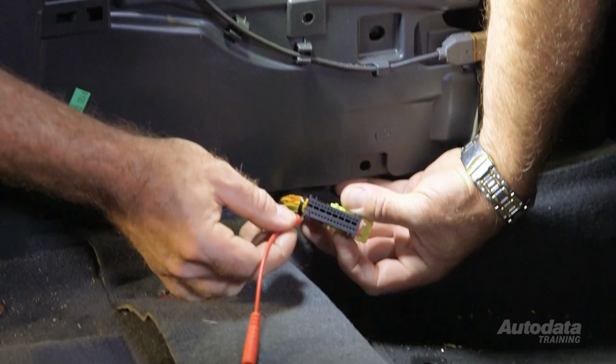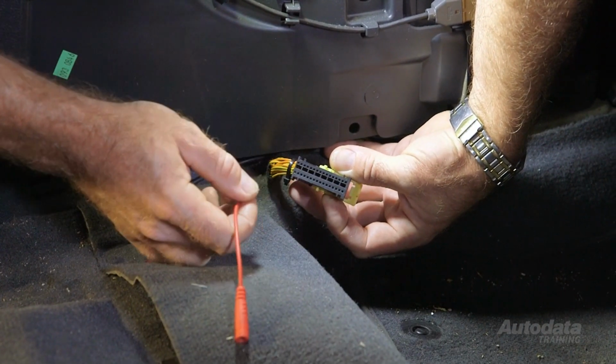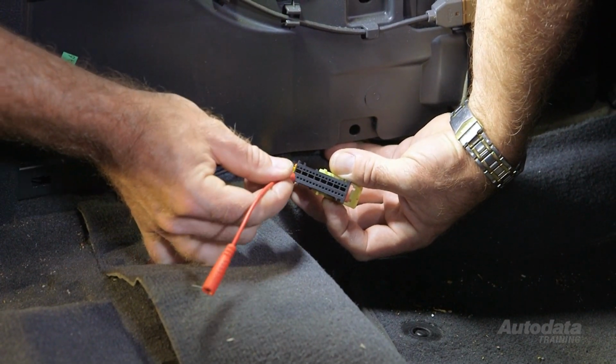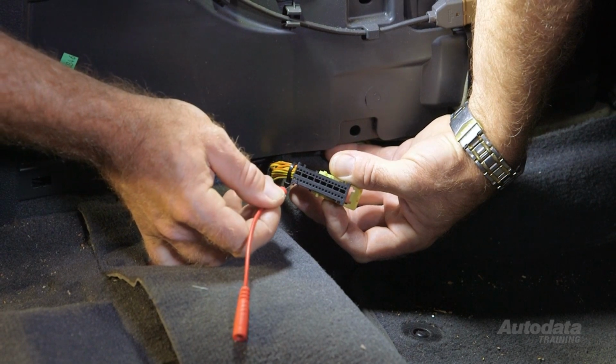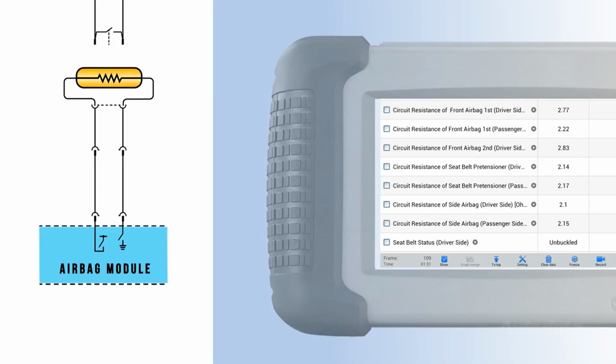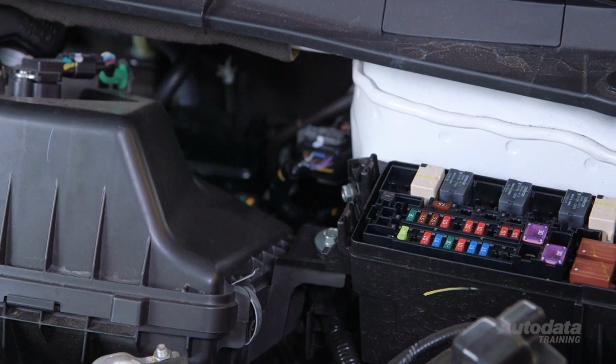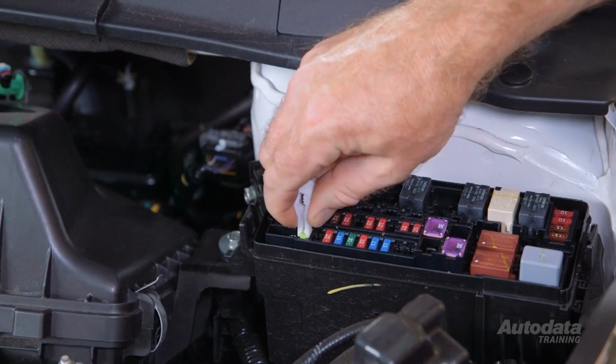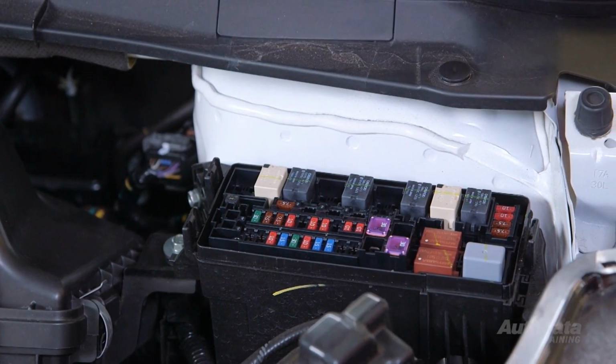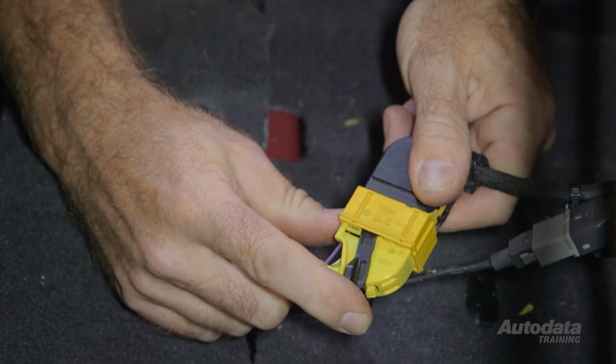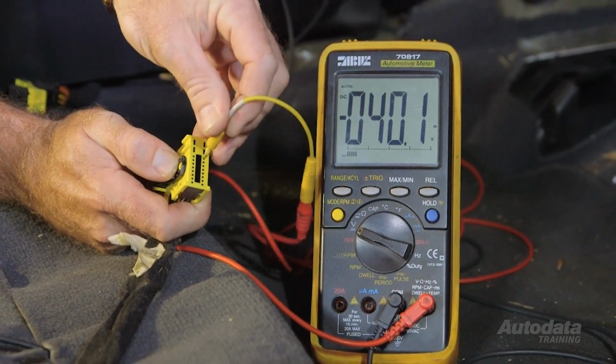If the value is still excessive, perform the battery disconnection procedure again. Check for terminal tension and corrosion at the SRS module. If this check was deemed to be okay, then the excess resistance must be in the control module itself. A DTC that presents as an open circuit fault can be treated the same as an excess resistance failure. Follow the same procedure we have just performed.